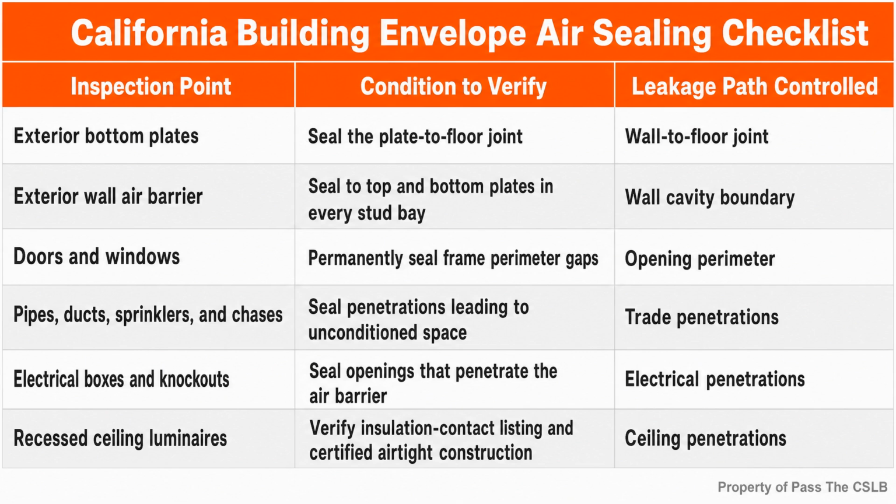A blower door test gives an objective measurement of the completed enclosure leakage. A calibrated fan is temporarily mounted in an exterior doorway. Exterior windows and doors are closed, and specified mechanical openings are prepared according to the testing protocol. The fan then pressurizes or depressurizes the enclosure to a target pressure difference of 50 pascals. That pressure difference makes air movement through leaks easier to detect and quantify.